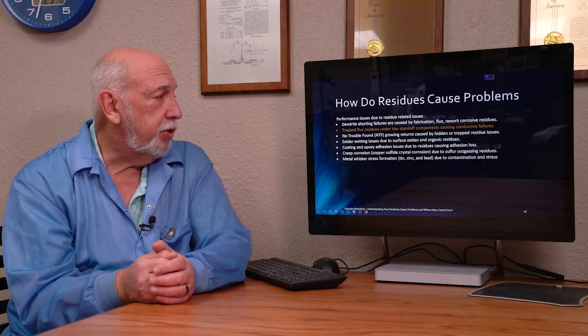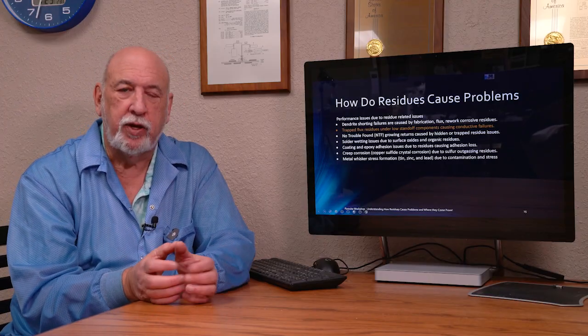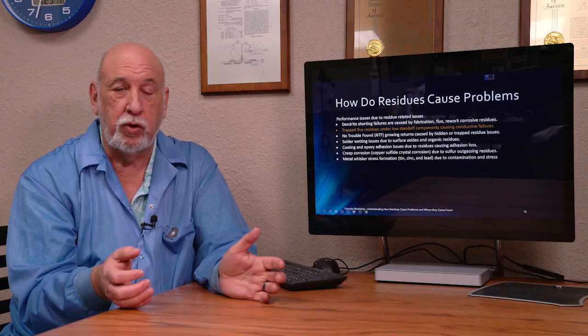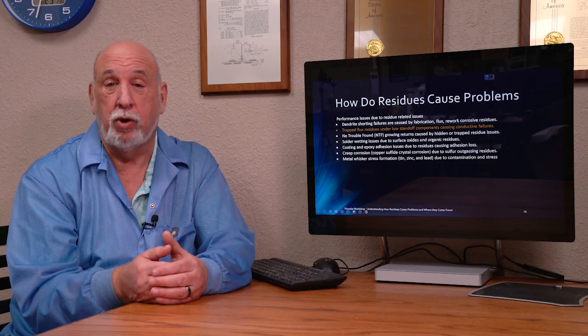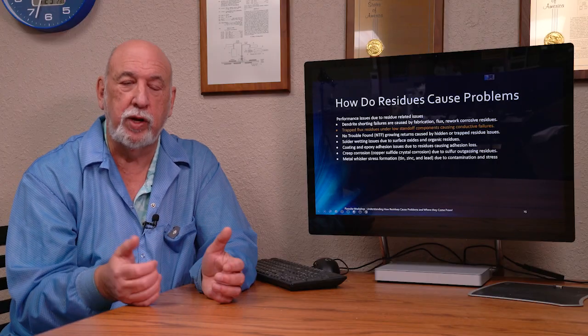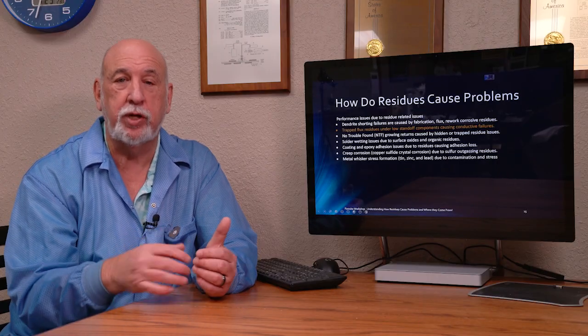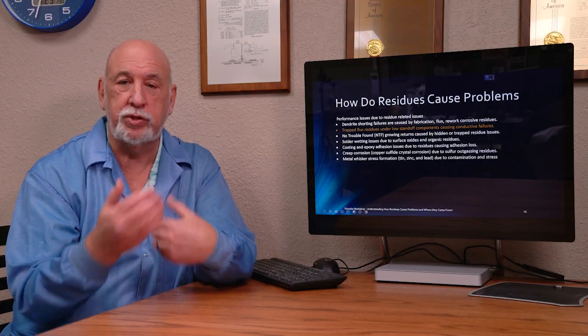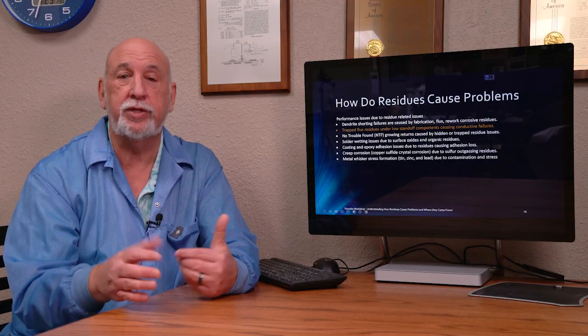One of the other things too is as we look at trapped fluxes, it's very difficult in the no clean realm as well as in the cleaning processes. Cleaning doesn't fix everything, and residues from a cleaning process also get trapped underneath these low standoff parts. So you have to make sure that once you solubilize the residues that you rinse effectively.